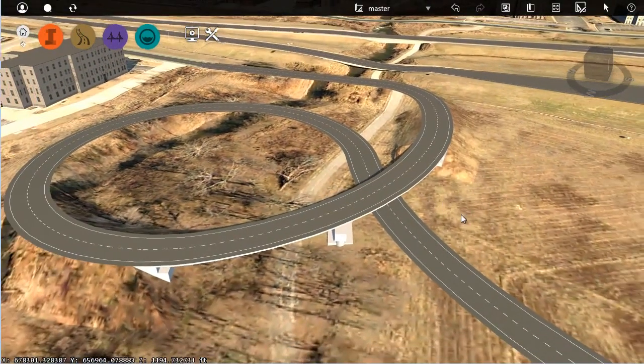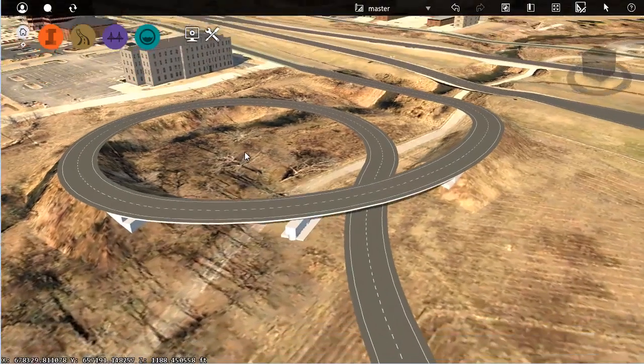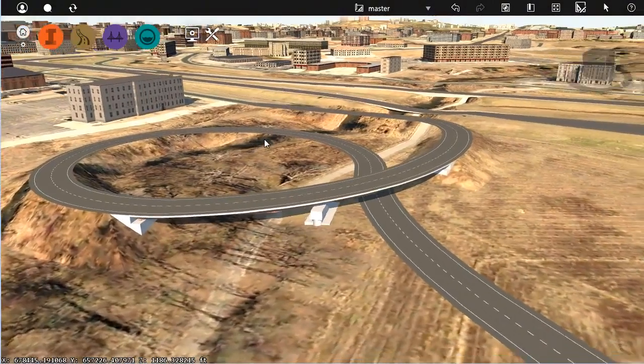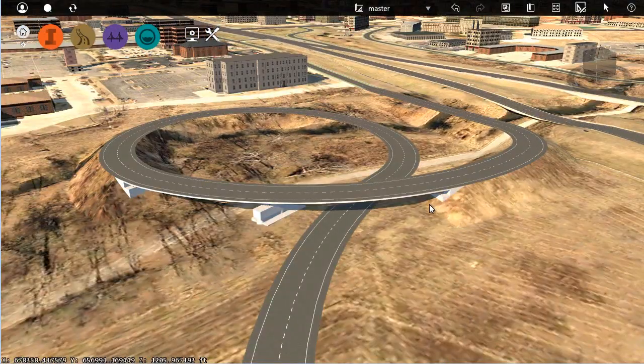That looks pretty good. So by using a 3D shapefile, I was able to leverage a complex alignment, still bring it into InfraWorks using my design information, and now by going through and segmenting this road, I can still leverage or access the power of a design road, even though this geometry started out as a spline-based road.